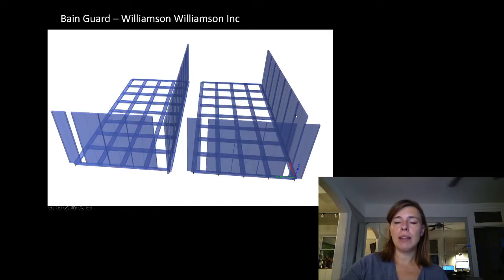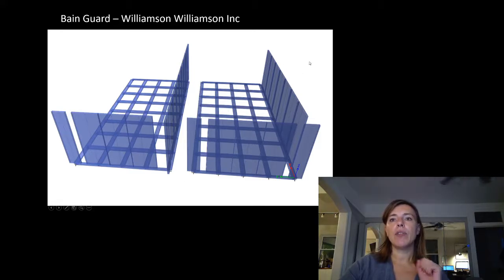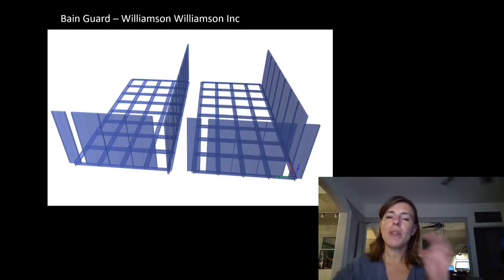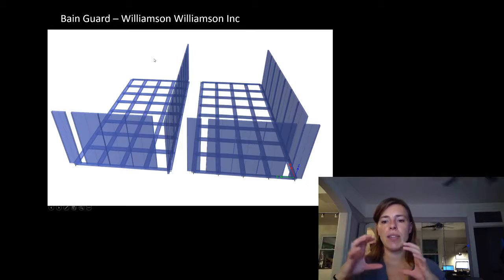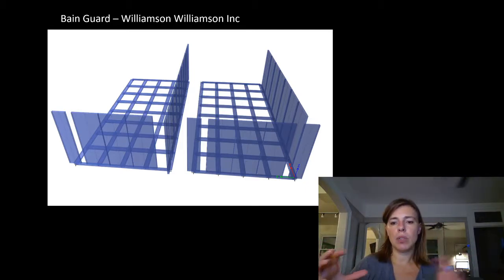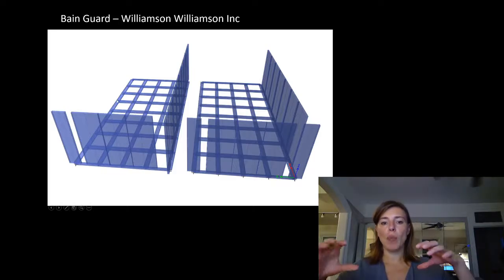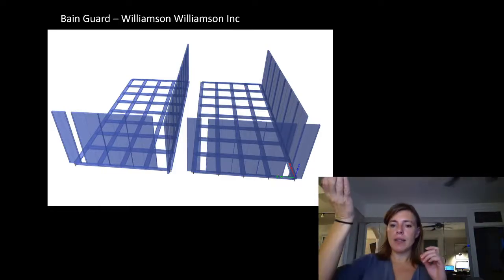Remember, I'm not modeling the glass, and this is my modeling software, which is not exact graphically. And I needed to look at a few different conditions. Like if I had put the guard over here and modeled my outward forces simultaneously, I would double. Basically, I needed to make sure I didn't have things helping me when I needed them to hurt me in the analysis. So the weight of that was actually helping me somewhat. And I needed to see where these loads dissipated. Where did this stop trying to lift my steel assembly up?